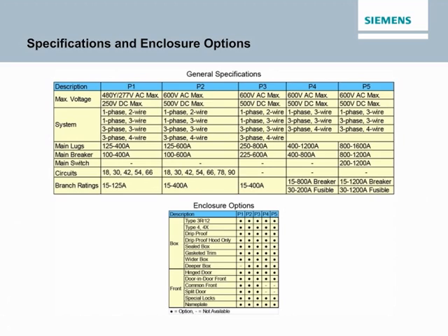All breakers except the plug-in type have bolted connections. The panel design provides bracing up to 200,000 amps, the UL short circuit rating. Keep in mind that this is not the interrupting rating of the panel, which depends on the circuit breaker configuration. Case-hardened, high-performance, thread rolling screws are used on the branch bus.